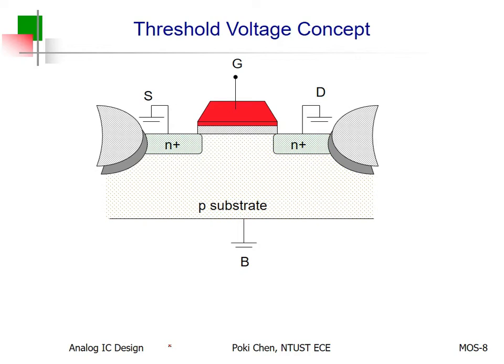All right. Last week, we talked about the concept of threshold voltage. What is that? For example, this is some kind of MOS. From the very beginning, we have two parasitic diodes connected back to back. It means the bias directions are reversed to each other. So from the very beginning, it is not conductive between source and drain. But how to make such an enhancement type MOSFET conductive? Actually, you need to kill those two parasitic diodes.